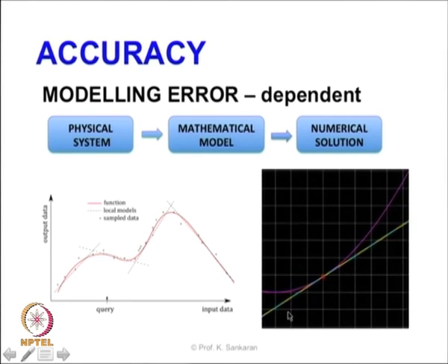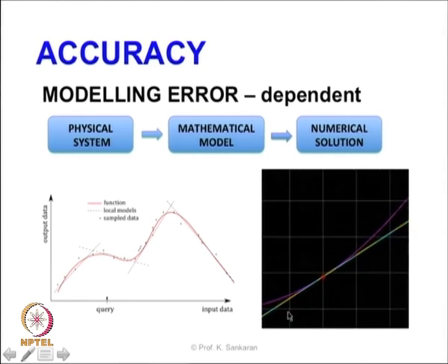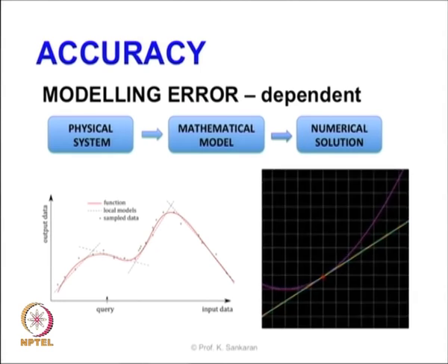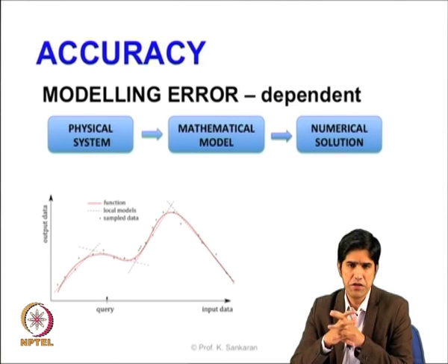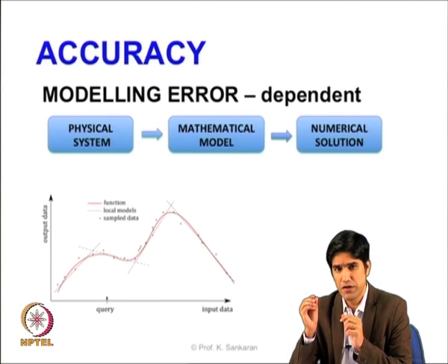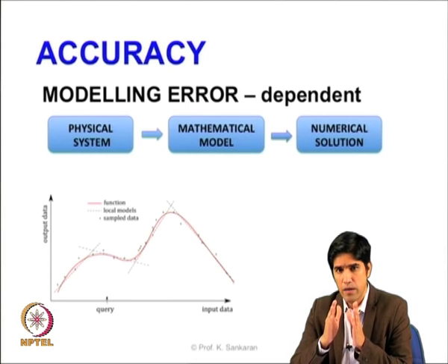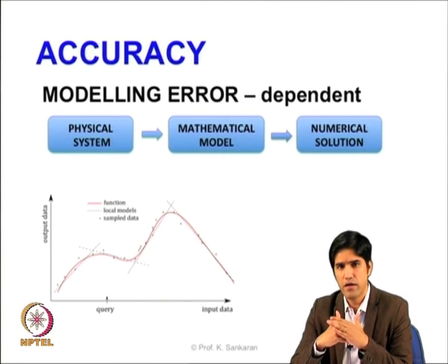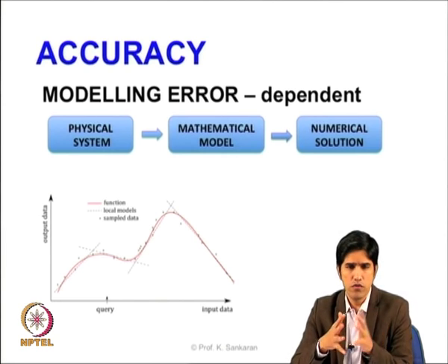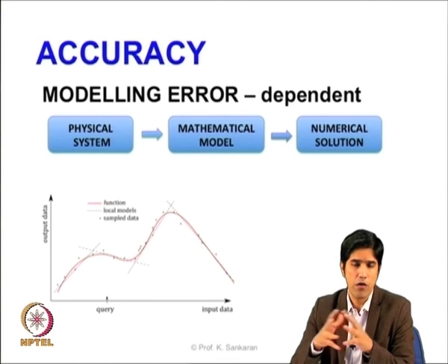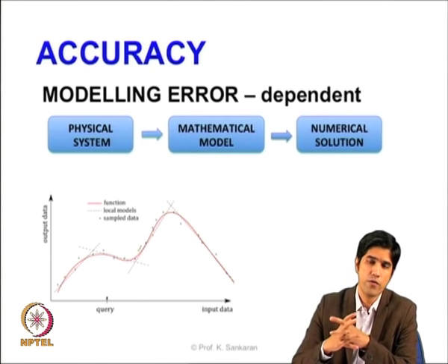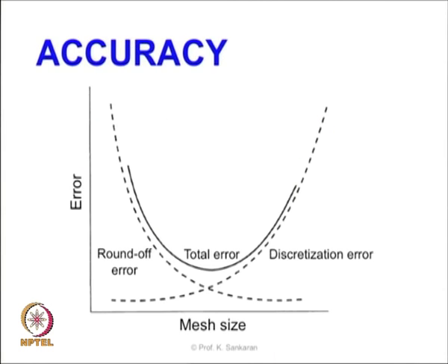So basically you see when you are refining the mesh finer and finer, when you are going closer and closer in the spatial and temporal discretization, your mesh size is becoming smaller and smaller. At the limit, whatever you are computing as the discrete value will be equivalent, or almost equivalent, to the value that you are computing in the continuous space. So that's the idea.